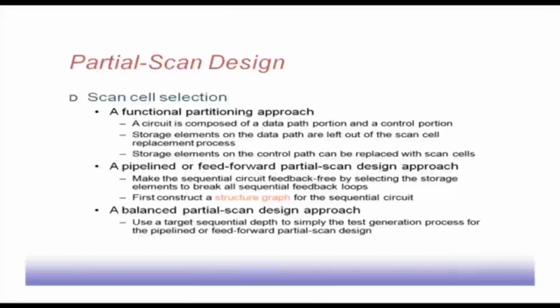Now, for controlling this data path, we need to activate several signals. First, the registers will get the value from the outside world, maybe in the first clock cycle. In the second clock cycle, maybe the adder will do the addition, taking the values from some registers and writing the result back onto another register. So, for the input registers I need to make their enable line high so that the values are available, and for the destination register I must give the load signal. For the adder module I need to give the add signal. So, these are done by the control part.